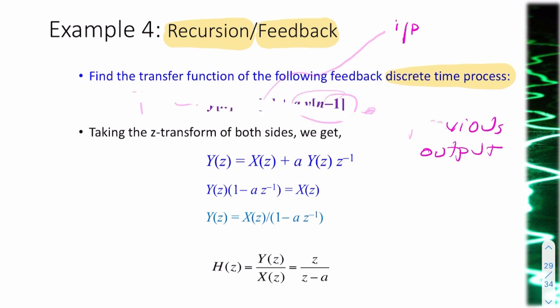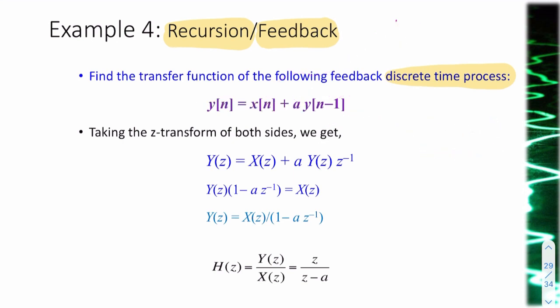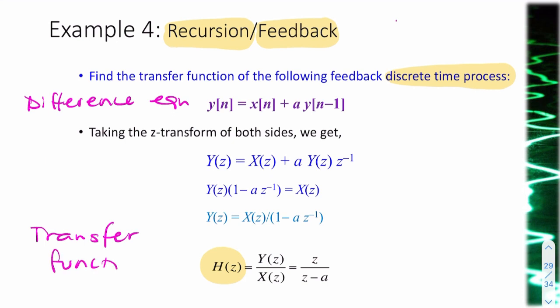So this is a difference equation. And what we're trying to do is, from this difference equation, to find the transfer function. So we're going from the difference equation to a transfer function. And it's actually quite easy. It's easier than it was when we were doing Laplace transforms, because all you need to do, it's a linear process, you can take a zTransform of each of these.